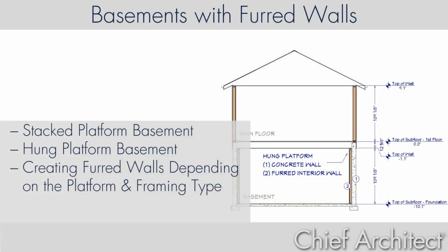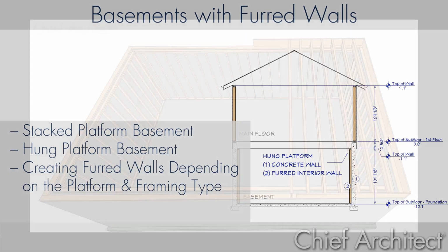In this video, I will cover the process for creating a basement type room with both a stacked and a hung platform. I will show you how to create and use a furred wall for both platform styles that will generate the correct wall framing. Let's begin by reviewing the two platform styles.